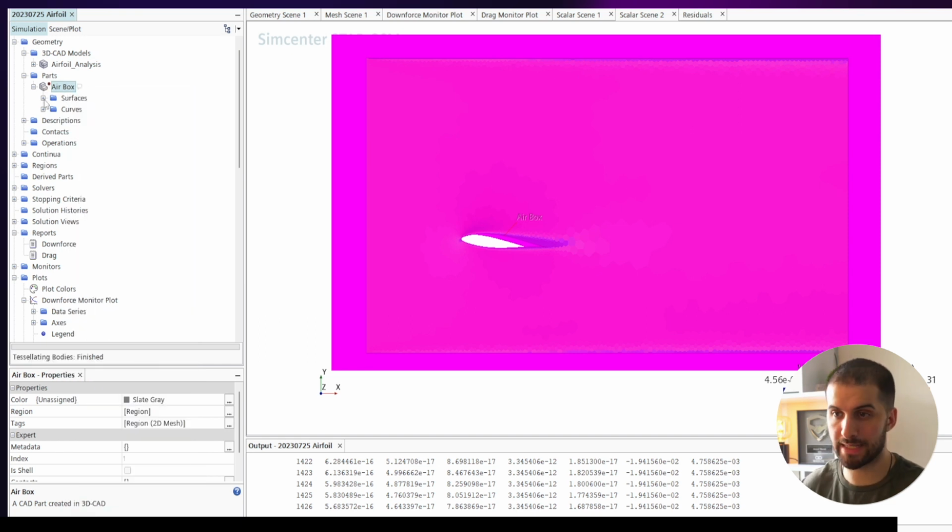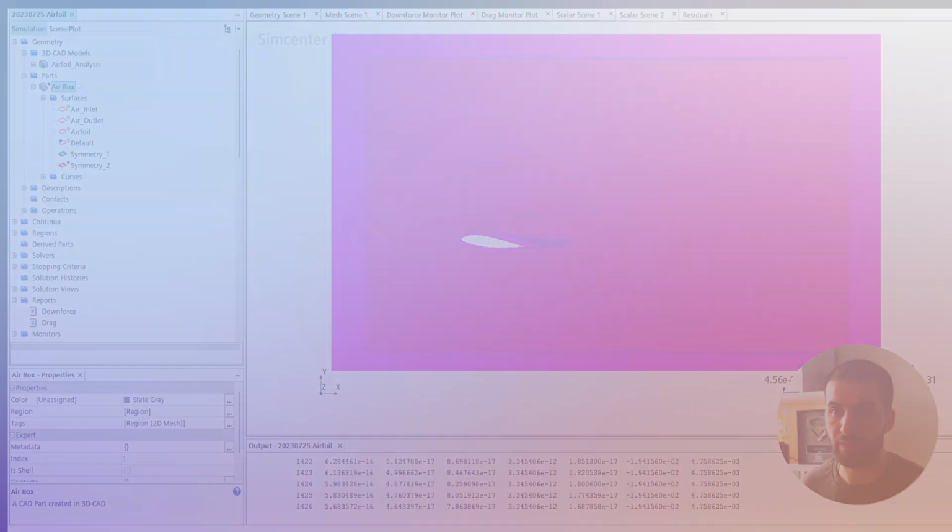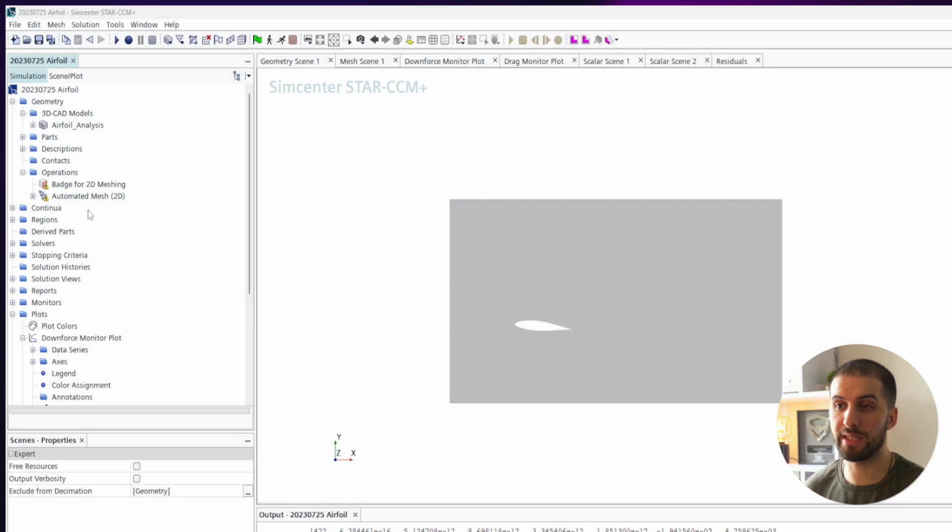Our 3D model is set up, our airfoil is in place, we set up the naming conventions for our boundaries, and now I think we can delve deeper into the world of simulation. Having created our 3D airfoil model, ladies and gentlemen, we now venture into an indispensable stage on our computational fluid dynamics journey, which is meshing.